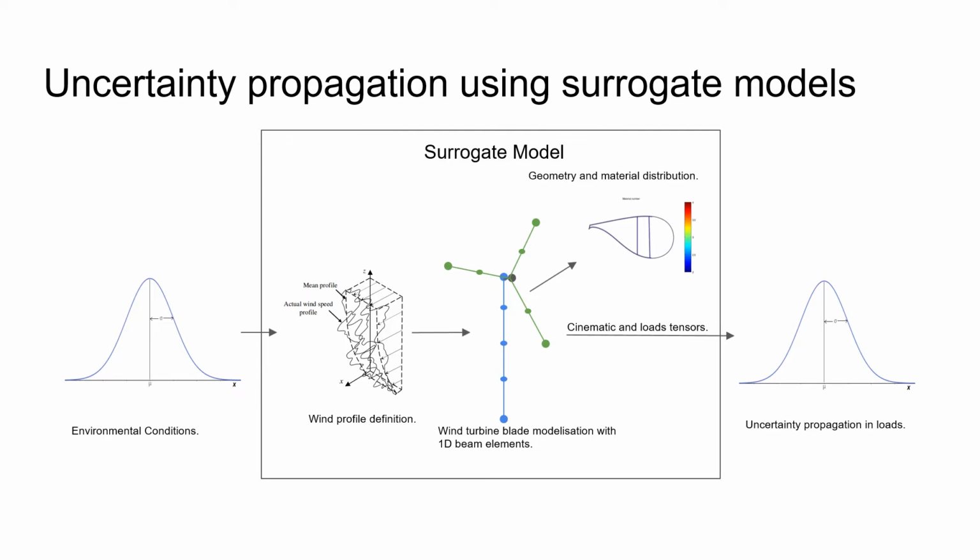To simulate wind turbine blades, aero-elastic simulation codes are often used, such as FAST from the National Renewable Energy Laboratory or HAWC2 from the Technical University of Denmark, because these tools couple the aerodynamic response with the elastic, hydrodynamic, control and electrical behavior using a beam representation of the wind turbine, leading to a nonlinear dynamic response.